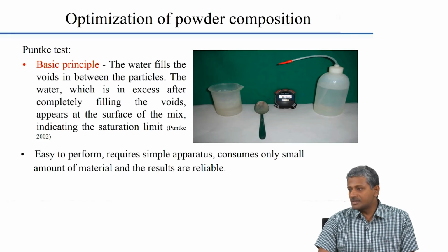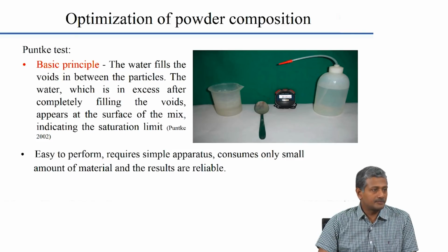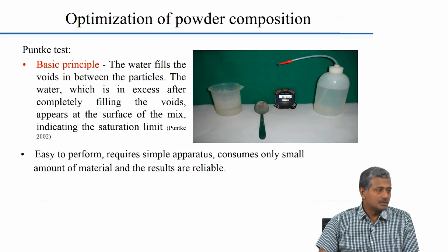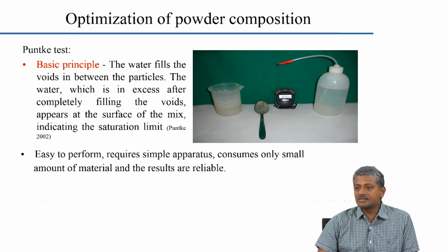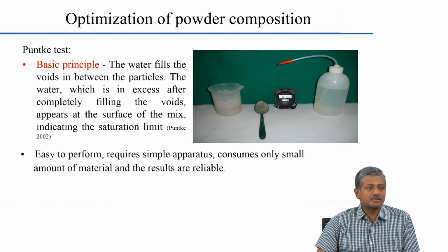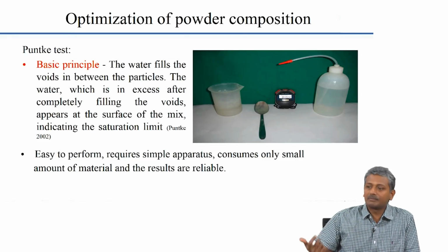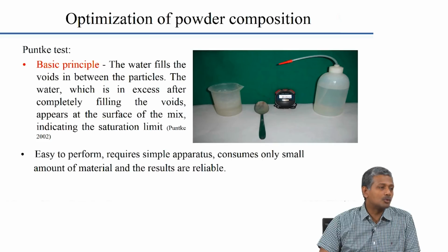Of course, both have to be self compactable, they need to pass all the tests. But if I have to choose the slump flow of the SCC for the column or for the slab, where do you think I need a greater slump flow? I need a greater slump flow for slab. Why? But then your application is much easier, no? All you have to do is move the chute around and fill up the space. Why do you need to really make it flow a lot?